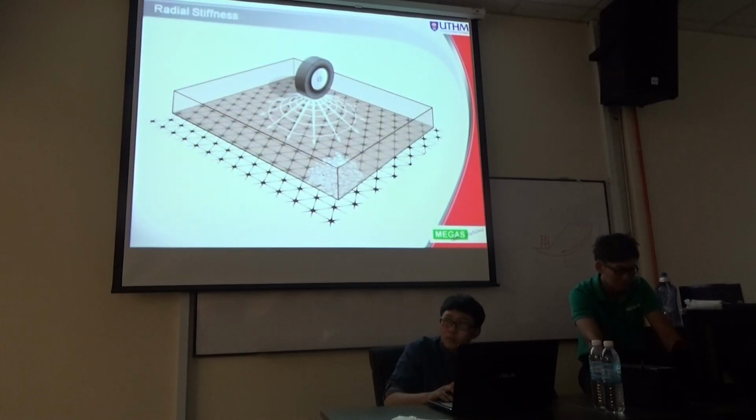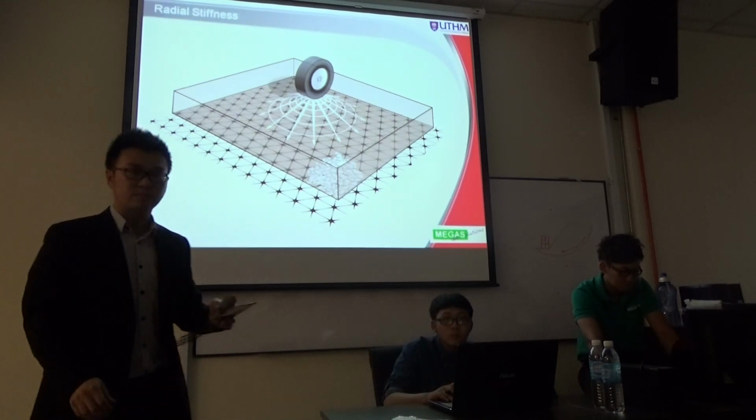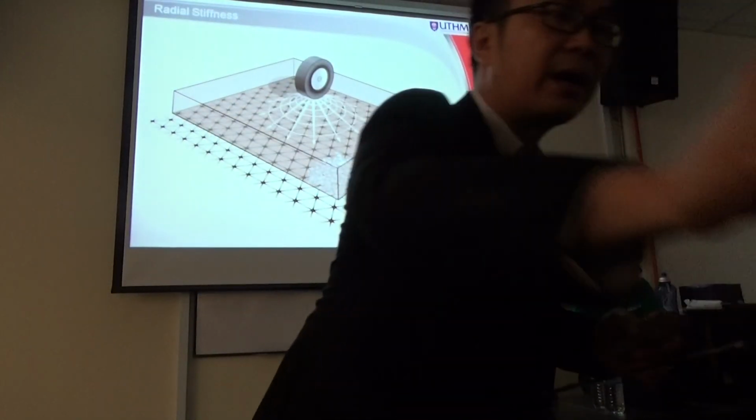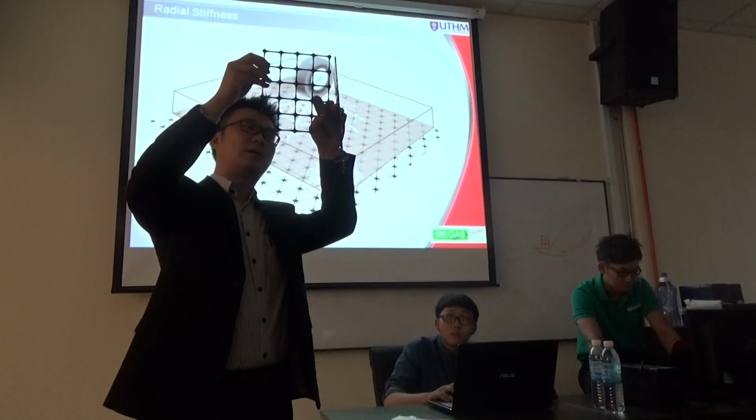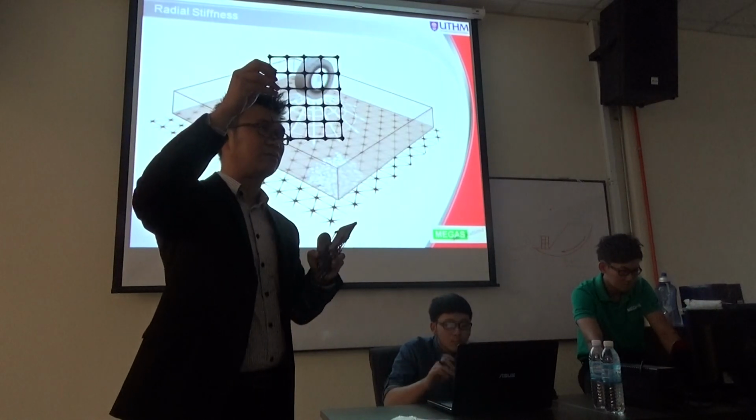Okay. The good thing about this triaxial geogrid is that, from the research, we can study how the load distributes through this geogrid. It is a multi-directional geogrid. Why is multi-directional important? For example, if we use it for a road, then probably a biaxial geogrid would be used. This is a biaxial geogrid. We have the X and Y direction only.